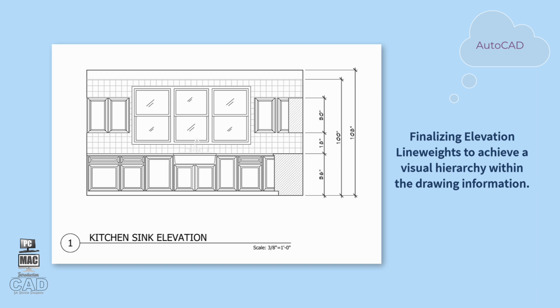Remember, in an orthographic drawing, only 2 dimensions are expressed at a time. To be able to manipulate the perception of depth in this flattened out type of drawing, we create a system where the darker lines appear closer to the viewer than lighter, thinner lines, which we perceive as further away from the viewer. Another goal of visual hierarchy is to help the viewer understand the drawing easily.